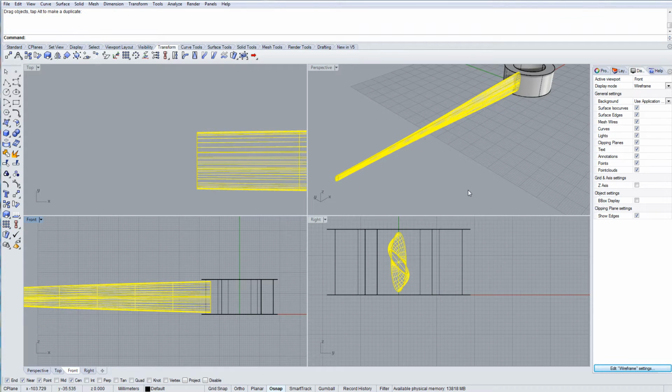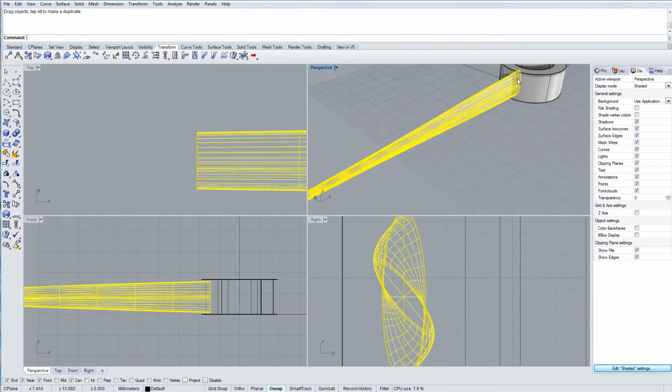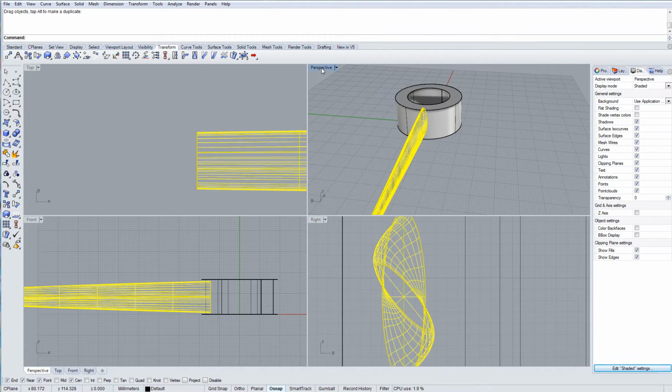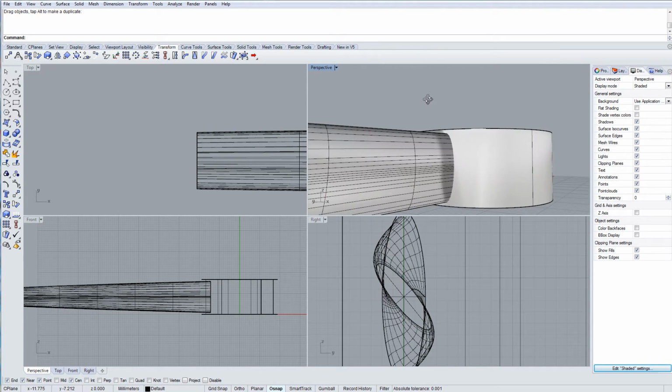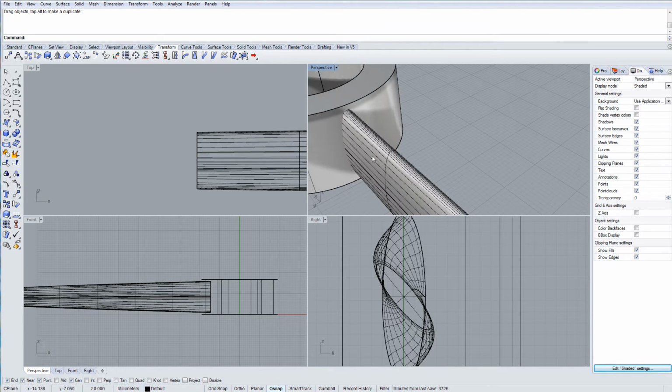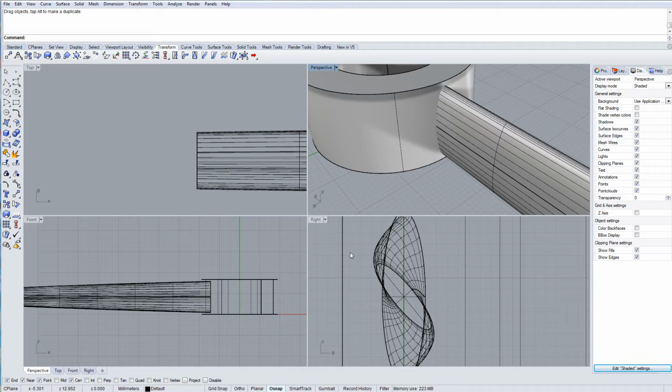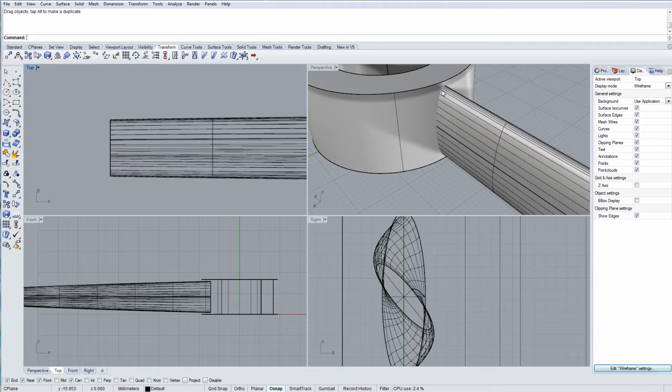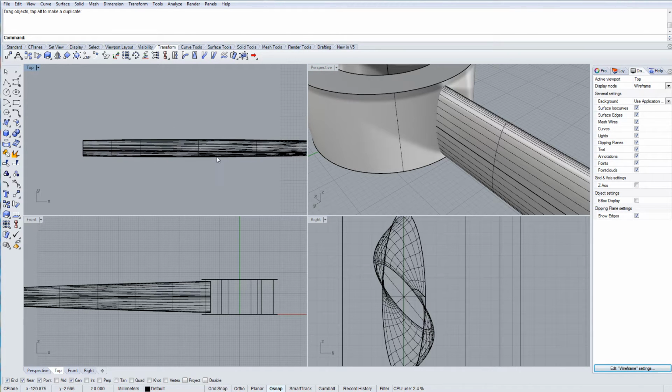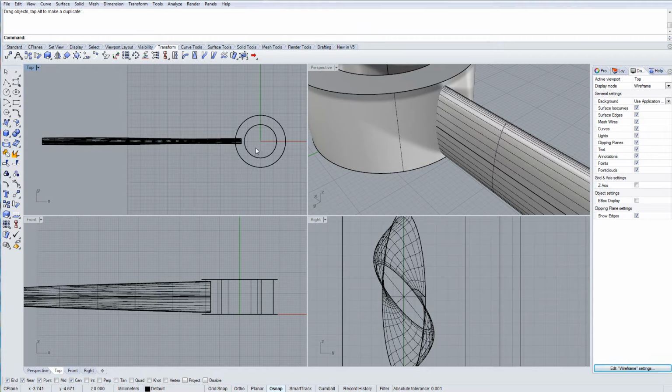There, something like that. Now I'm also going to be filleting this, so I just need to look and make sure that I've got enough room around the outside to fillet it with a decent size of fillet. And that seems okay. I'll probably have a 2mm, maybe a 1mm fillet around there would do it. I'm actually probably only at a 0.5mm fillet, but we'll have a look at that when we come to fillet it. So now I've twisted it, I'm going to array this around the center.